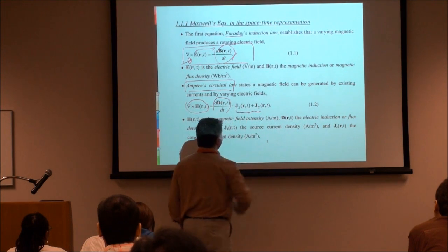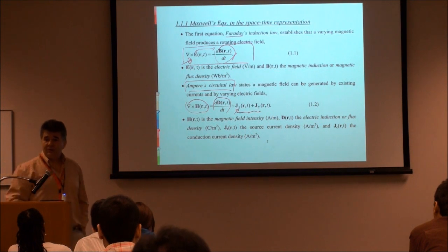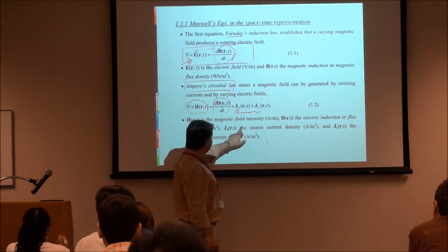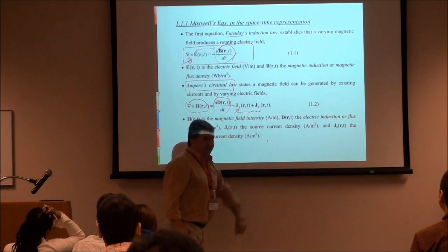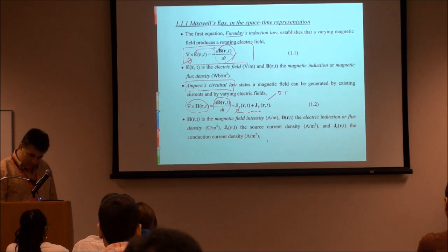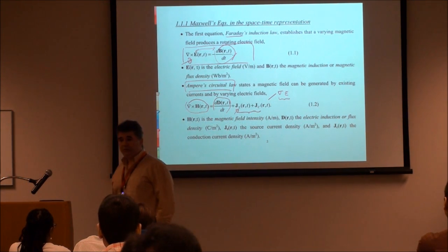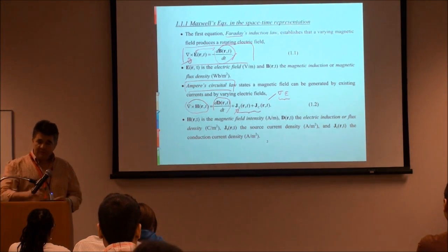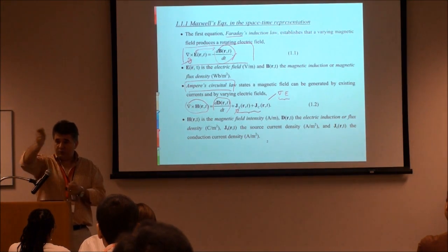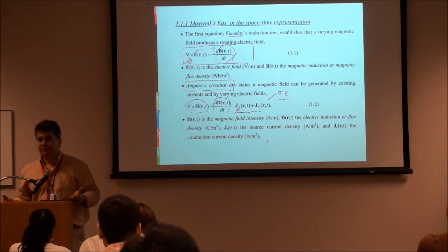You can have a source like an antenna that has a certain current through it, and that's why we call it JS. This is a density of current. Okay, it's a surface thing. And I can have a conduction current of the form sigma E. In other words, something that will happen in high conductivity materials like metals that you told me earlier. Okay? What this current means, first of all, is I can have a certain current that I plug in there and it's flowing through. Not so much in optics. We're moving towards that. The scales are too small, but very common in antennas.